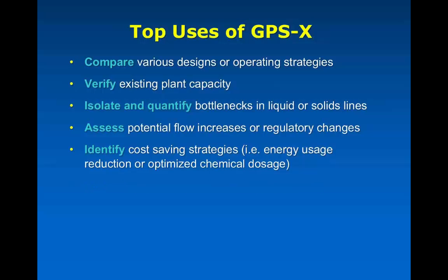We get quite a bit of interest from people who want to use the model to study the impact of retrofitting an existing plant with a new technology. So, for example, probably the most common version of that we get is: I have a plant that's running conventional activated sludge right now, we're thinking about adding IFAS plastic media, and I want to know how much more capacity that will bring to my plant. And that's certainly something you can do in GPSX by putting that right in there, having those two plants running side by side so that you can compare the new and the old and see what kind of difference you get.